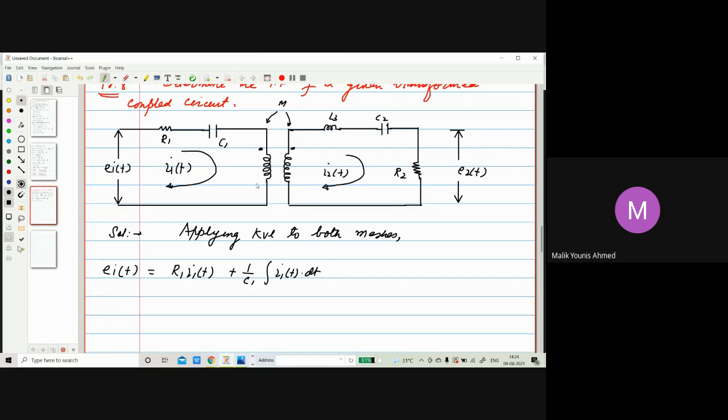plus, now voltage across, this is here inductor L1, this is L2. So voltage will be L1 di1 by dt, that everybody knows. That is a self inductance. What will be the mutual inductance? Mutual inductance will be because of the other effect, and the sign will be negative because here the current is moving from dot to coil, here it is from coil to dot. So that is the opposite direction, and that you know already. I have taught you a number of numericals in network.